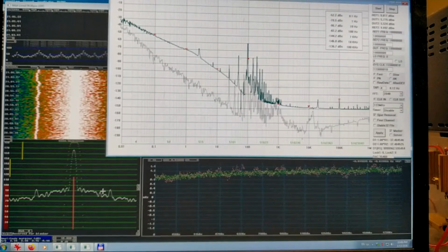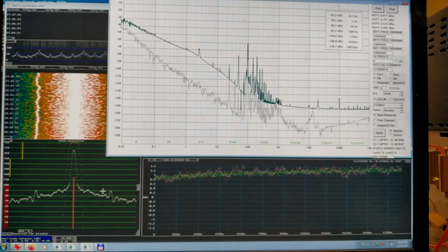In this video I will show how I try to improve my reference oscillators for phase noise measurements. What you see on screen now is a frequency shifted rubidium source. Frequency shift is obtained by dividing 10 MHz, which is from that rubidium source, by a factor 512.